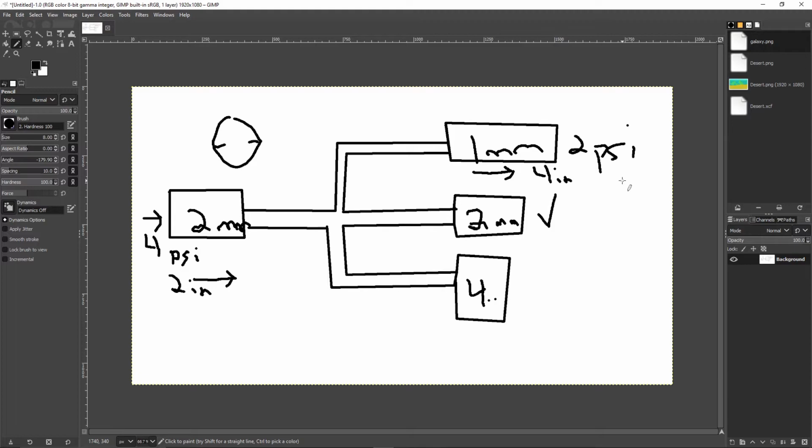Every example I can think of is the opposite, which is the bottom one here. So in real life, your master cylinder and your brake calipers, or your master cylinder and the slave cylinder on your clutch, which is specifically what we're talking about today, we're going to do it this way. So this guy at the bottom that is twice as big in bore is going to have twice as much brake fluid pushed against it, which means it will exert twice as much force, which is great.